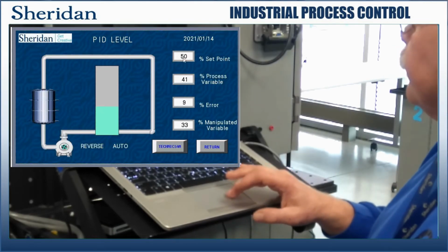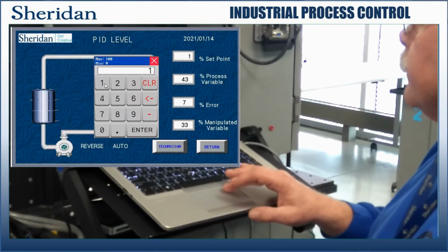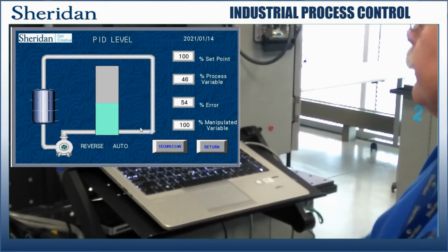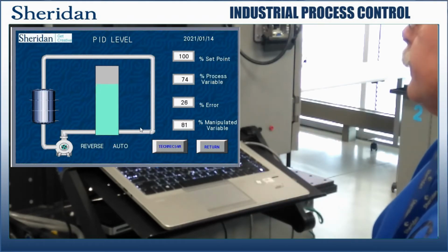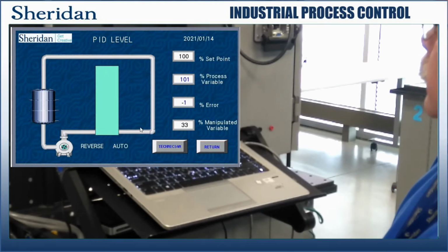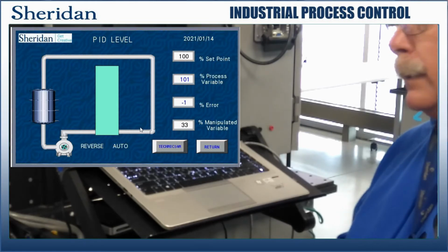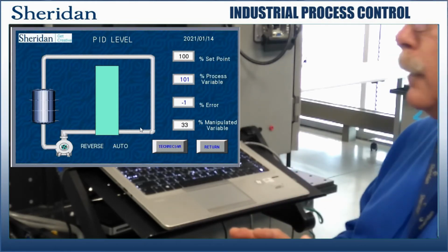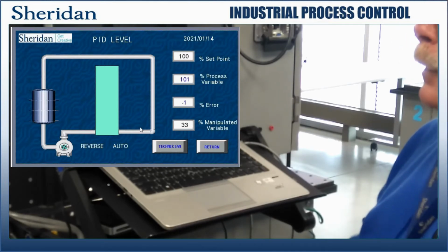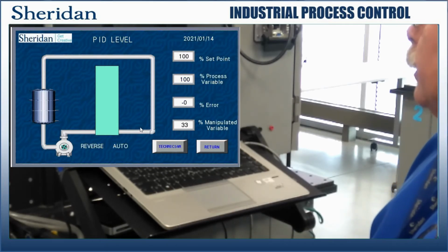this to 100% and see what happens. See if I overshoot. Notice it goes right up. Well, I've got it at 100%. It's up to the 100%. Just overshoots by a little. It doesn't go way over and above like the other one went to 82 out of 75% process variable.